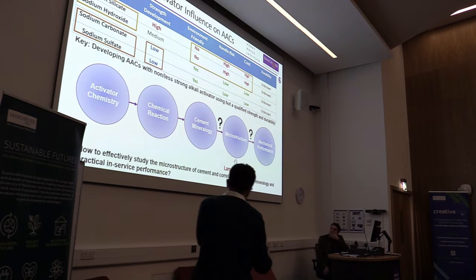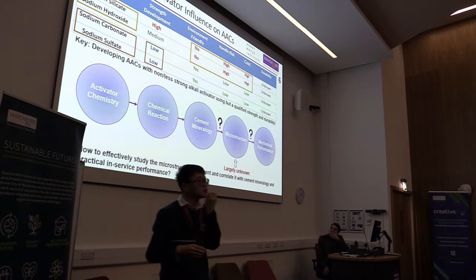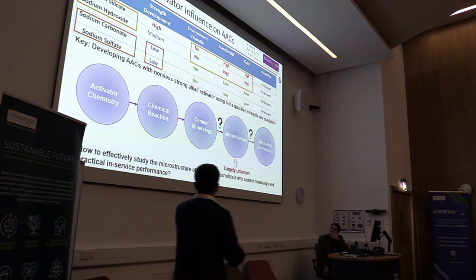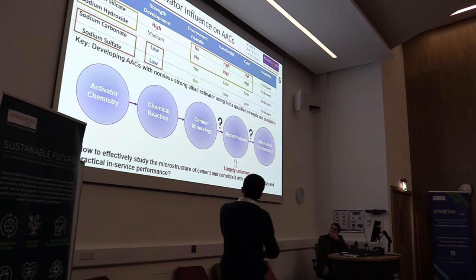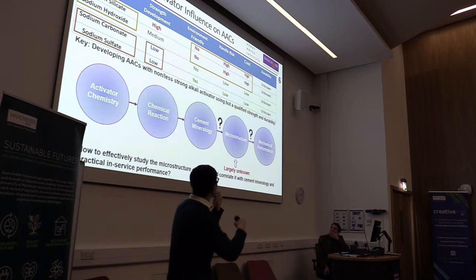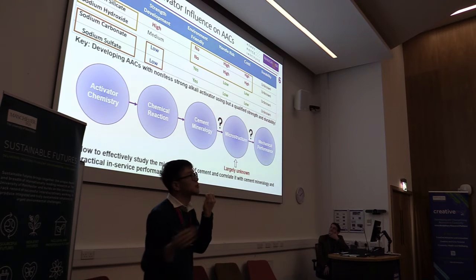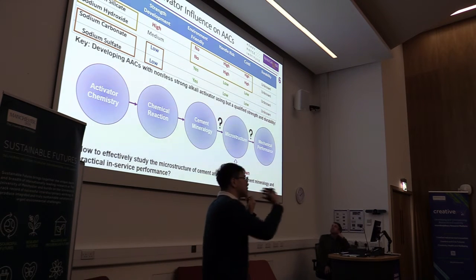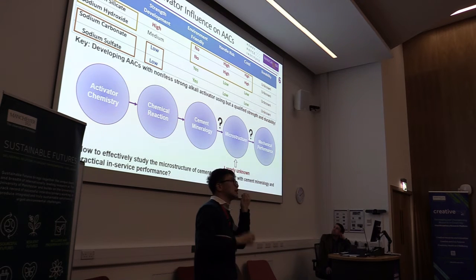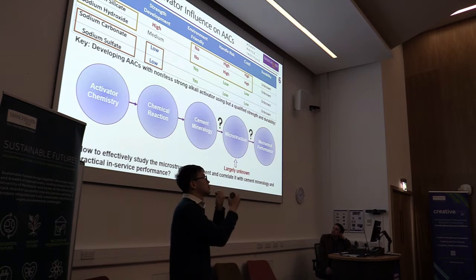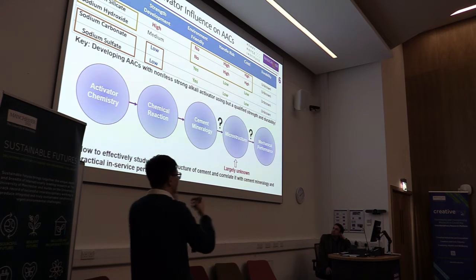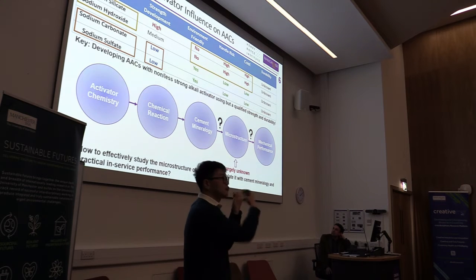Incidentally, sodium carbonate and sodium sulfite are near-neutral activators to produce alkaline activated cement. They are both environmentally friendly, with less pollution, low risk, and low cost because they are naturally abundant. But the main problem is low strength development. The reaction of these two activated cements is slow. The mechanical performance, the strength, is not